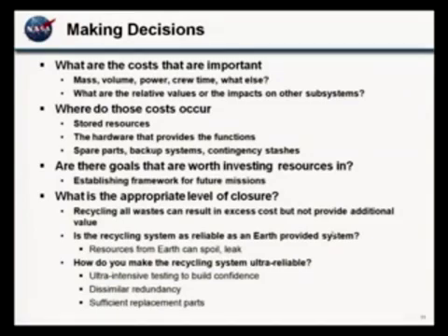But mass of the life support system is not the only thing to think about. If you have a large volume, lightweight component, you are essentially adding to the structure of the vehicle required to house everything, and so you're adding shell mass. If you have a lightweight but high power component, you are adding to the solar arrays and adding to the batteries required. So you are putting loads on other parts of the vehicle.